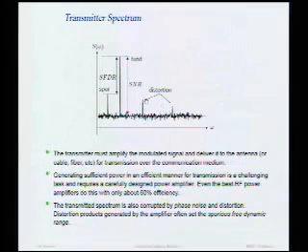In fact, there's usually a spectral mask that we have to satisfy, which is again set by the standard of communication that we're using. So, of course, I can use filtering to get rid of these harmonics, right? That's not too bad, big deal. Build a little low-pass filter, you get rid of that.